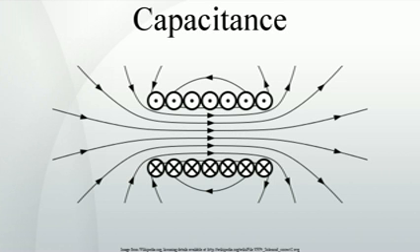Few electron devices. The derivation of a quantum capacitance of a few electron device involves the thermodynamic chemical potential of an n-particle system, whose energy terms may be obtained as solutions of the Schrödinger equation. The definition of capacitance with the potential difference may be applied to the device with the addition or removal of individual electrons. Then this is the quantum capacitance of the device. This expression of quantum capacitance may be written differently, which differs from the conventional expression described in the introduction, where the stored electrostatic potential energy differs by a factor of 1/2.